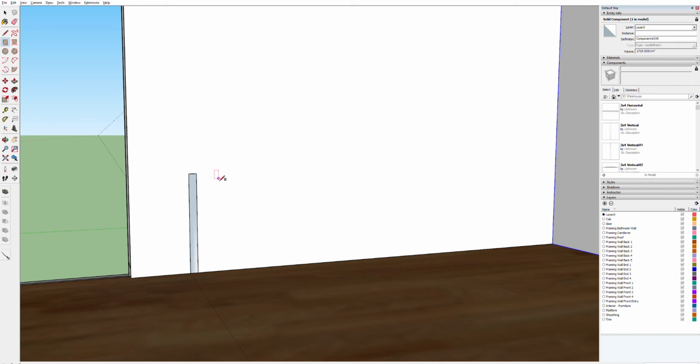Oops, you know what? I didn't actually write down the dimension. Let me go grab that. Okay, our treads are 9 inches. The way these treads generally work, or this calculator was showing us, is the tread sitting on the stringer. So the stringers are actually going to have to be a little bit deeper to give us a 9-inch tread. So we have to make these treads 9 3/4. You'll see why that makes sense in a second. So 9.75, 0.75.